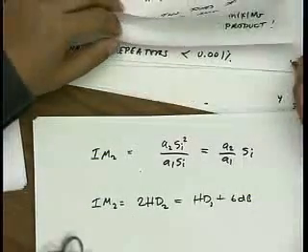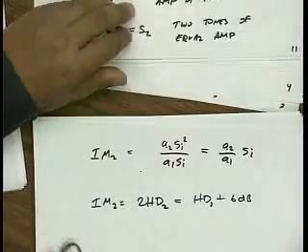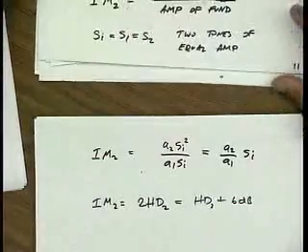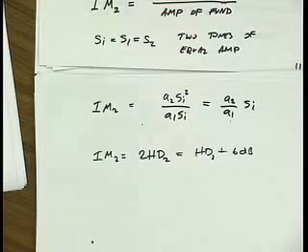What's the difference between omega 1 and omega 2 usually? Okay, so the question is, what's the difference between omega 1 and omega 2? It can be anything, right? This holds arbitrarily. So it could be two tones very close together, could be two tones very far away from each other. Regardless, they'll generate intermodulation terms.